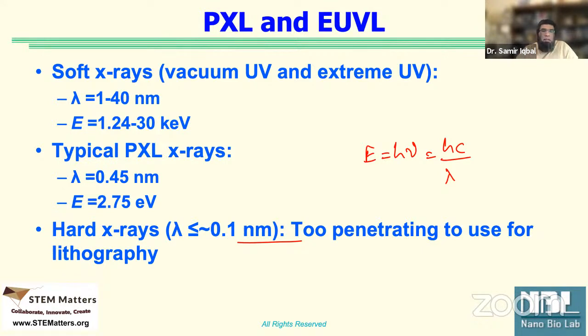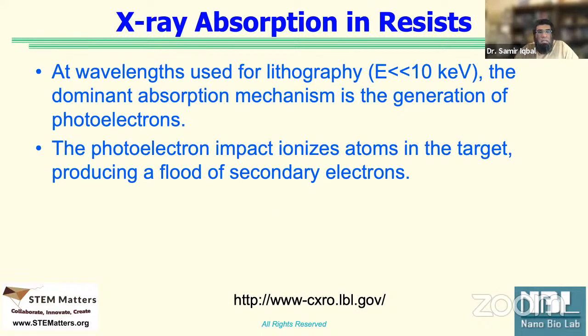We keep on pushing, we get into hard X-rays, which is 0.1 nanometer. Yeah, we can have very small features theoretically, but the problem is too much energy. The energy is too high and problems of mass come in. So now we know that when we get to this energy, 10 or less kilo electron volt, we want to have the absorption of those waves, so the photoresist can undergo chemical changes. But if they don't absorb, they keep on passing through, and the photoresist will not get exposed.